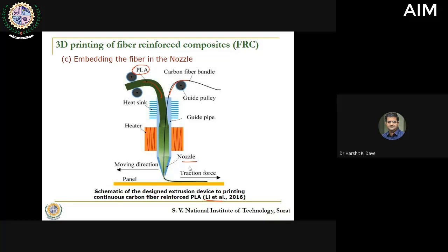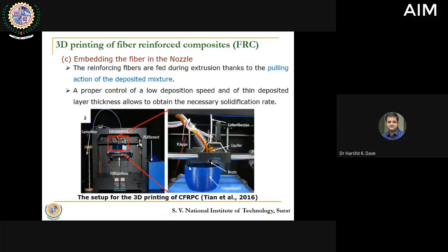And so there has to be certain design changes in the nozzle, and its opening may be required to be slightly enlarged than what the standard size of 1.75 mm is concerned. So here this is what happens, and they have reported this to be working well. The part